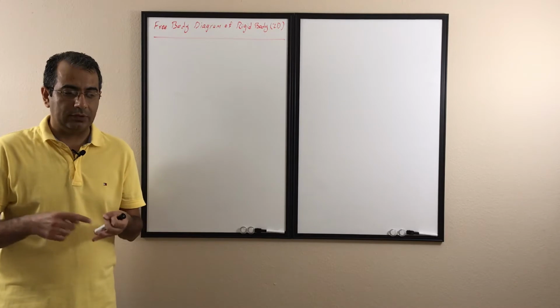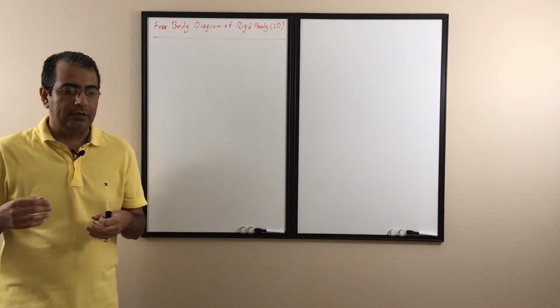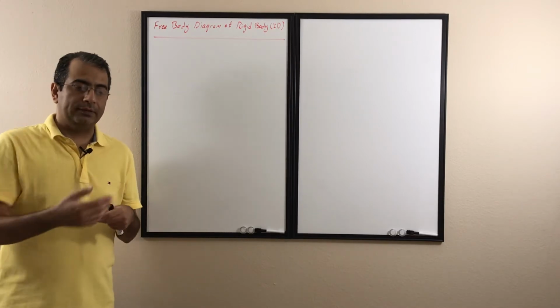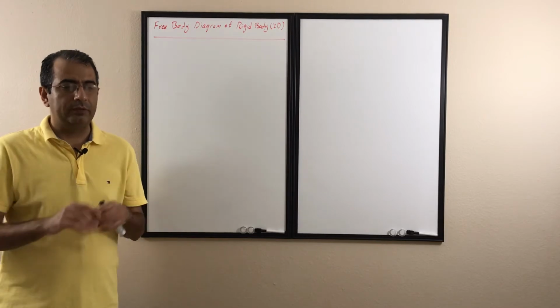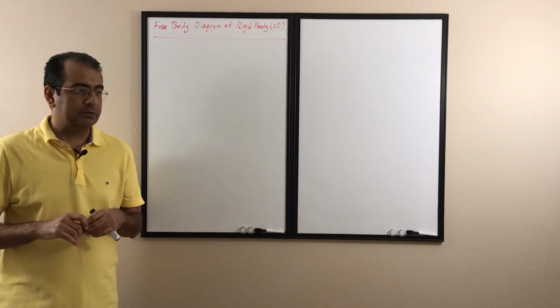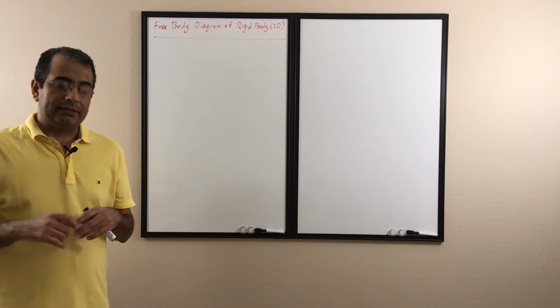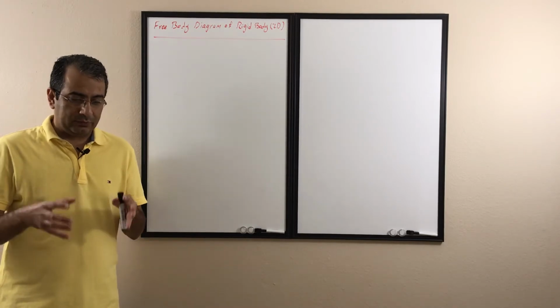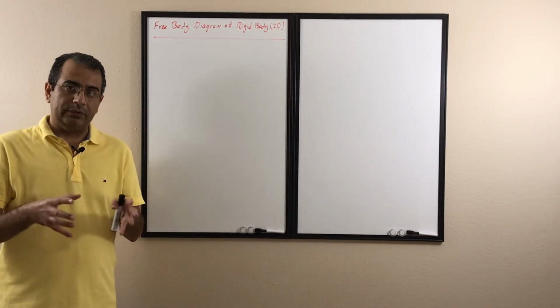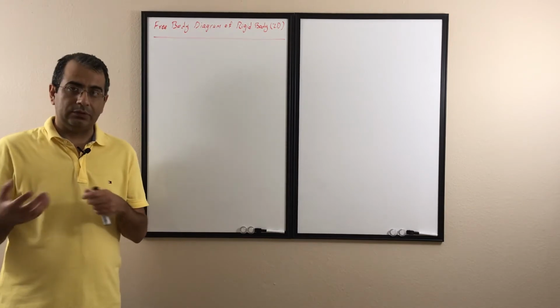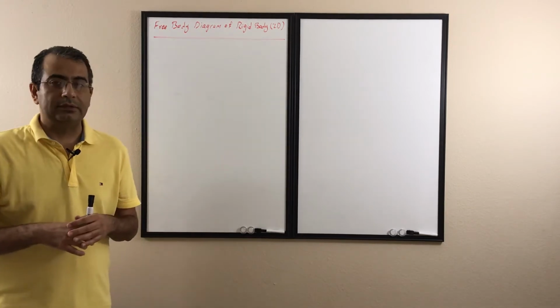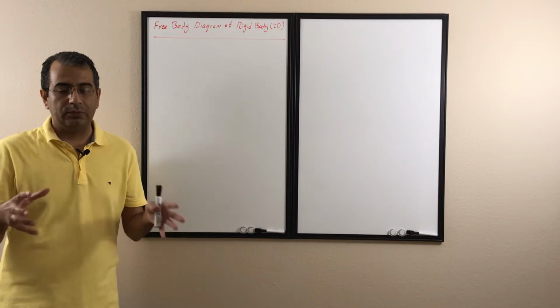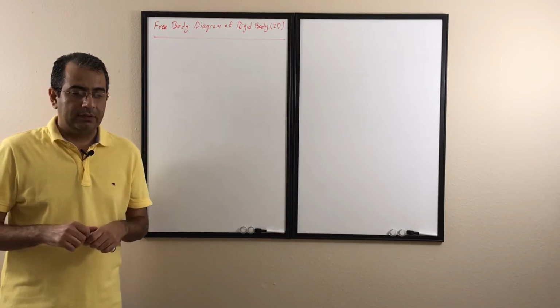One type is the active forces, the ones that want to make the object move, like the weight, or if we are putting any external forces on it. The second type of external forces are the forces that want to keep the object in place, and these are the forces that result from having the support, so the support wants to keep it in place.